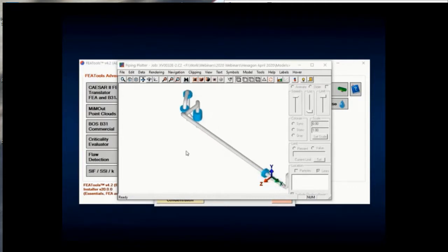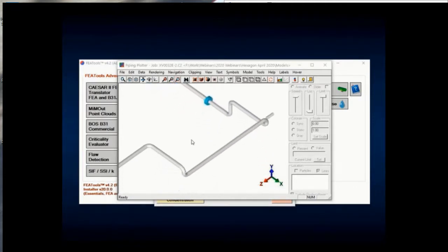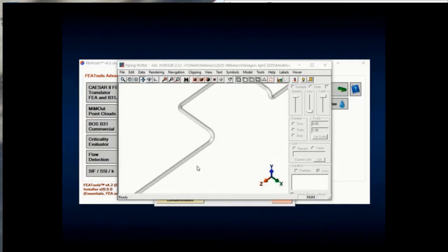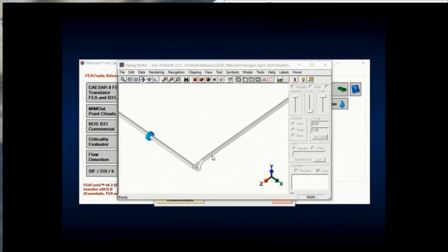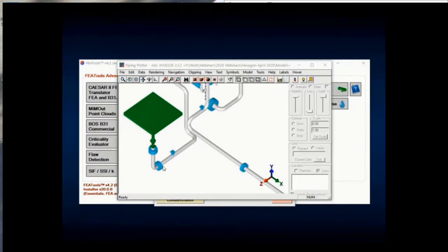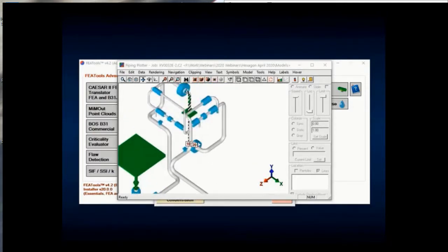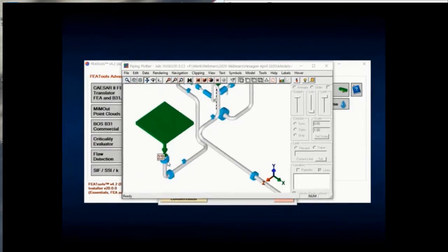If flanges occur at high bending moment locations, then we'd like to find places in the model where there are lower moments. And so you can pick literally any node in the model to have a flange calculation performed for that node. So we're just stepping through the model, identifying each of the present flanges.